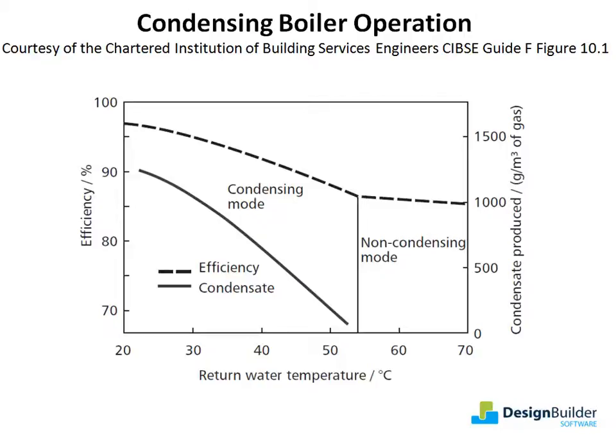Floor heating systems generally have a slow response time, as the heating pipes provide indirect heating via the mass of the floor screed. It takes longer for the screed to heat up and cool down than emitters such as radiators and convectors. This can result in zone temperatures deviating from set point temperatures if the heating or cooling loads in the zone change quickly, through solar gain or natural ventilation cooling, for example.